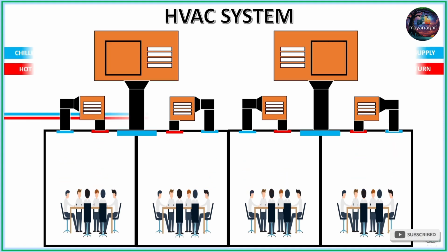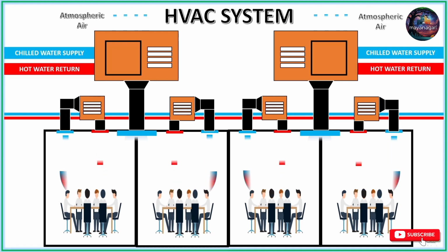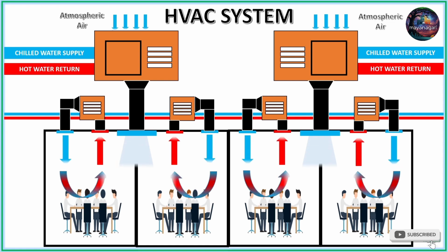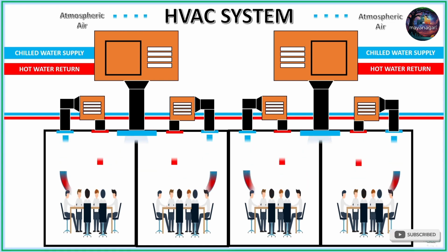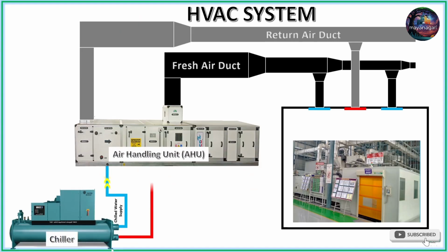Both the units consist of a cooling coil through which chilled water of the same condition is supplied to produce chilled air. Both the units work together in a smart way to replace AHU for a larger environment and produce better results. So, where does this chilled water come from? A chiller is an electrical unit that produces chilled water by using refrigeration effect.